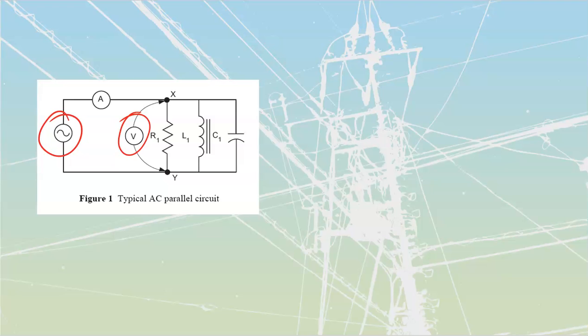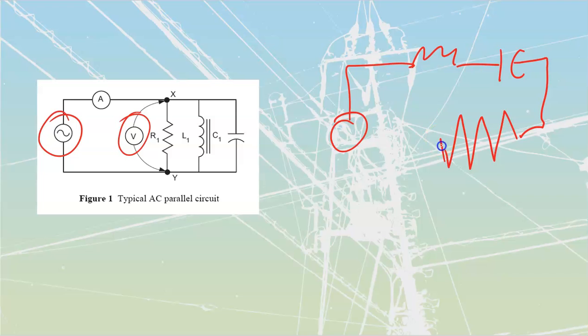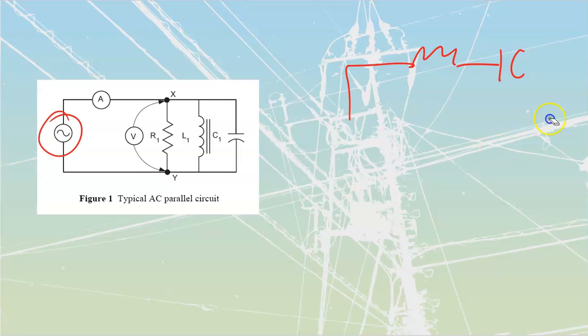When we were dealing with vectors inside of a series circuit, we used current because we knew that inside of that series circuit we had our inductors, we had our caps, and we had our resistors. We knew that we had that current that was going to be the same through every component. Well, it doesn't actually go through the cap, it goes to and from the plates, but you get what was going on. It was the same value of current that was utilized by each one of these in their calculations. Now what we're looking at is the same value of voltage across each one, which means that the way we draw everything is also going to change.